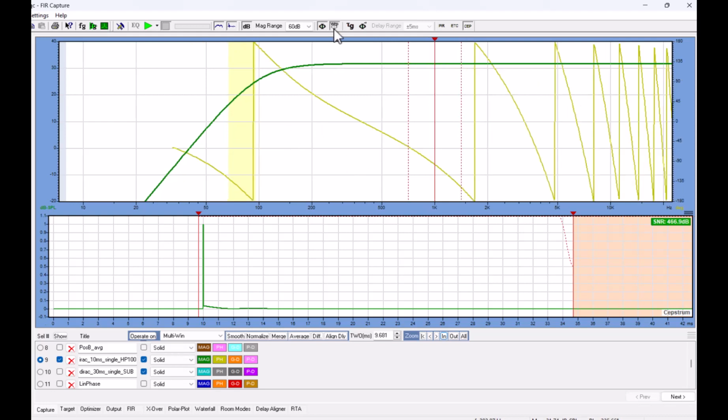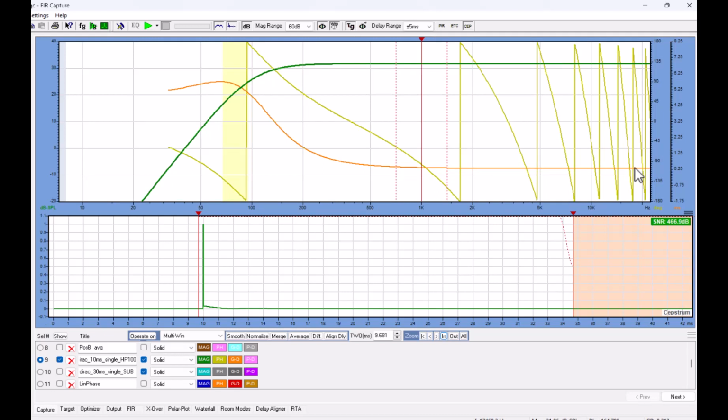And that's the idea with wrapped phase, that you zoom in, and these vertical lines here actually have no information, because it's only this curve here which contains the information. Compare that to the group delay. There you can see how the time varies through the system.